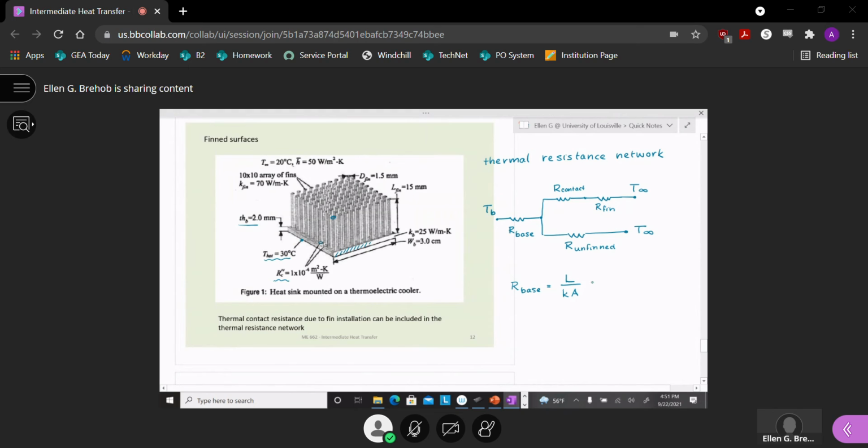If I put it in terms of this problem, they did 2 letters, thickness B, so that's all thickness, and K_B and area B. If I looked at contact resistance, I always think that double prime means per unit area already, but when you watch the units, you'll see you got to divide by area.